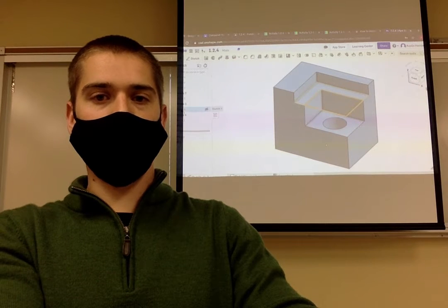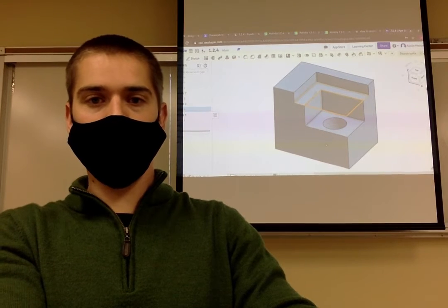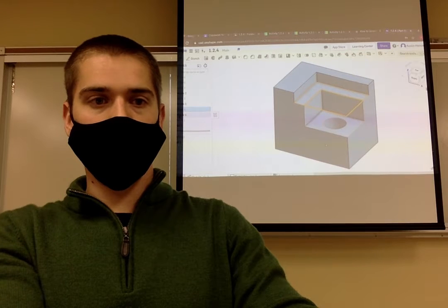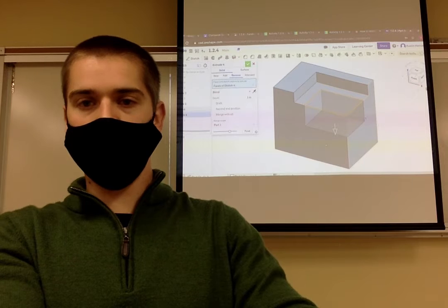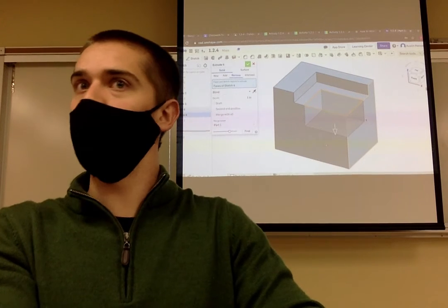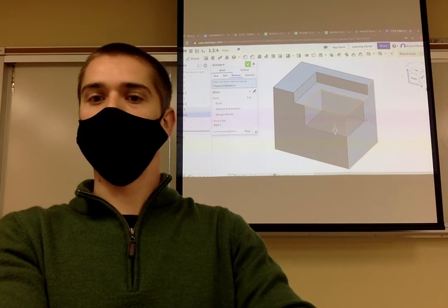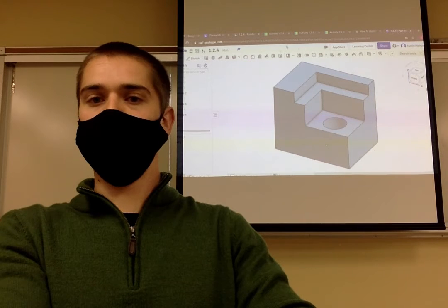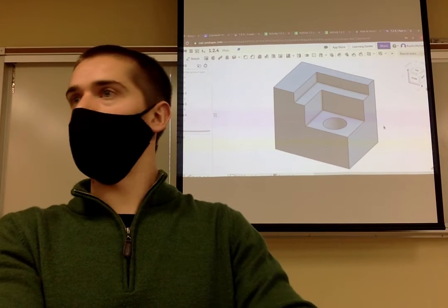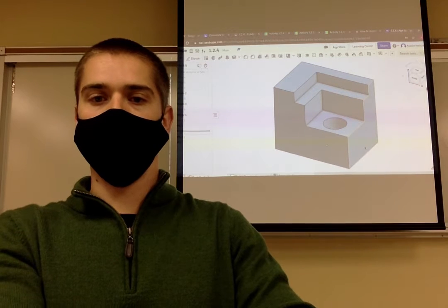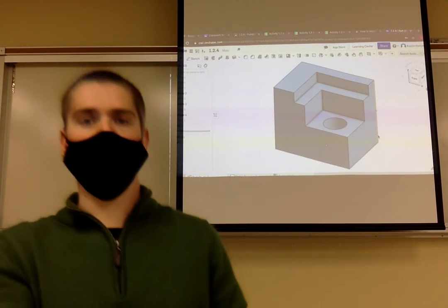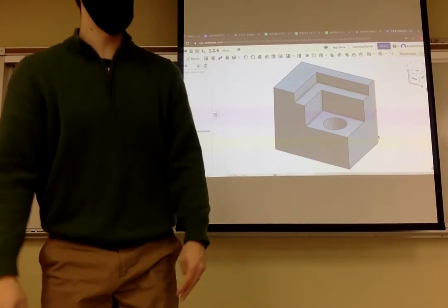Then I made another sketch for this cutout, and I took that correctly dimensioned shape and extruded it the correct dimension down. I removed that extrusion. And that gave me the shape I wanted, really straightforward, rather than trying to build it up with these weird L shapes. So I just wanted to share that piece for you guys.